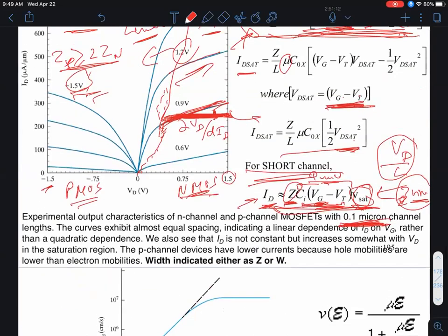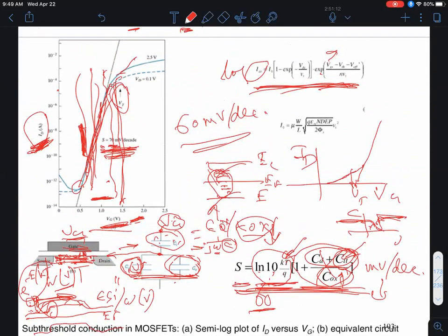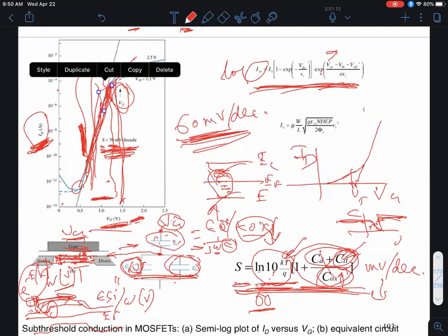Well, I forgot to mention that. Let me go back for a second. So in modern transistors, the threshold voltage is designed to be around 0.6, 0.7 volts. And that's really determined by this subthreshold slope of 60 millivolts per decade, okay? Why is that? Well, if my VT is say 0.6 volts, where the transistor is turned on, if I go down to 0 volts, so assume that I have 60 millivolts per decade, the ideal case, right? So from a VT of 0.6 volts, every time I go down by 60 millivolts, hopefully the current goes down by a factor of 10, right?